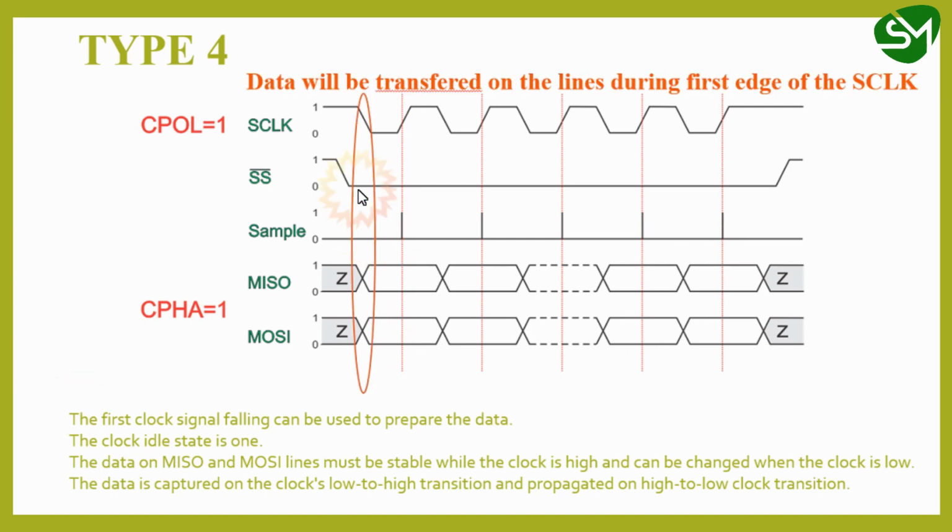And in the same type, the data will be changed or transition in the miso and mosi lines in the first edge of the clock. That is, in every first edge of the clock.